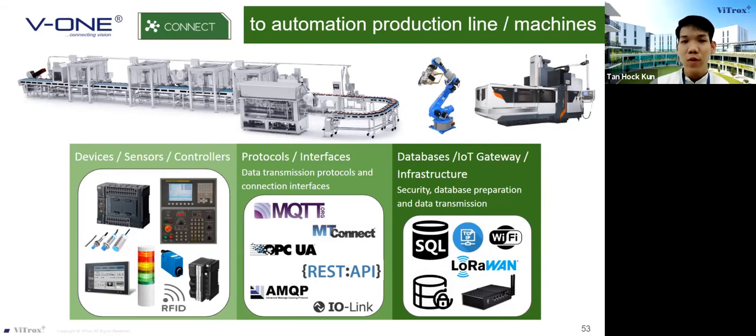Besides the direct connection from your machine data and also production equipment, V1 can also work compatibly with various kinds of devices, sensors, machine controller, or PLC. For example, for legacy devices that do not have a common machines communication protocol to be used or a proper data extraction method, we often help our customer to install external sensors like proximity sensors, tower light sensors, as well as temperature sensors on top of these legacy devices to get the system connected.